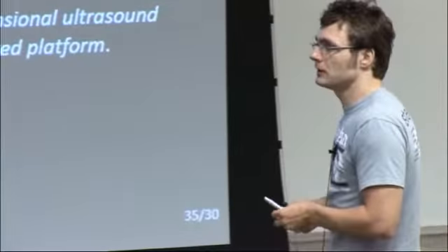So what people typically do is they say, okay, we can do microphone beamforming in the computer. We can do it offline. So we'll just use one source, splash everything with sound, and record it with a lot of microphones, and then do microphone beamforming offline. The limit on the frame rate is then quite high because you just need to send one chirp, tick, and then only do the receive beamforming.